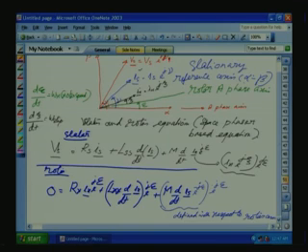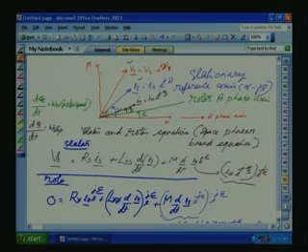So this is very simple. I will again go through this equation so that you will be able to understand the transformation from one reference frame to another. So if you see here, I will again explain for clarity. We want to define the stator voltage and rotor current with respect to a common reference axis. This is the alpha axis, this is the beta axis, and alpha is placed along the A phase axis and beta is perpendicular to that one.